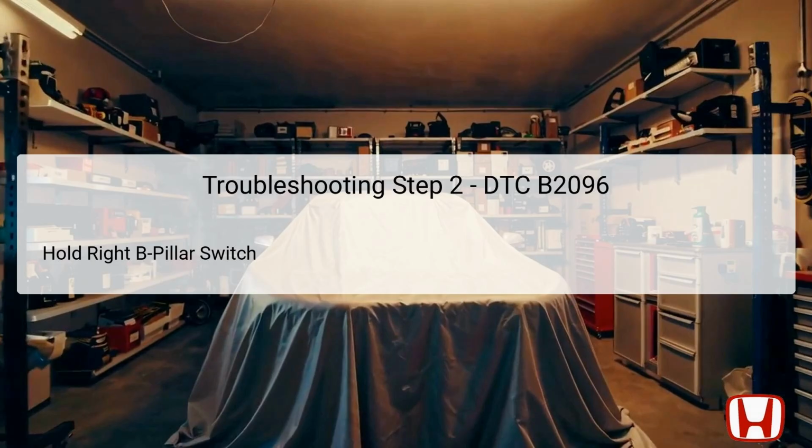After performing this step, the technician should again use the HDS to check for any new or recurring DTCs. Observing the results post-activation of the switch helps in determining whether the issue was merely a temporary fault or if further investigation is necessary. After recalibrating the right B-pillar switch, the technician should check for any DTCs using the HDS again. This step is vital as it allows for immediate feedback on whether the previous actions taken were effective.